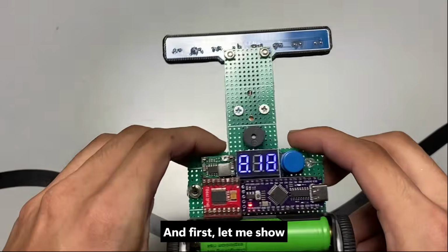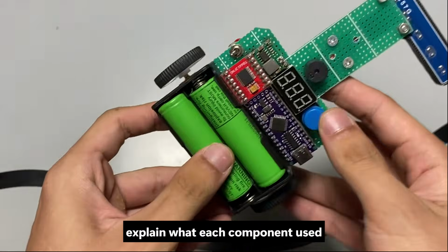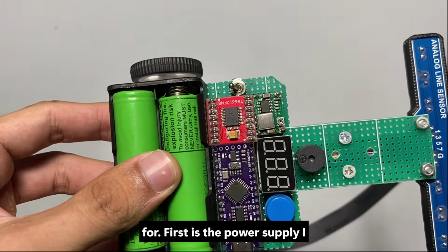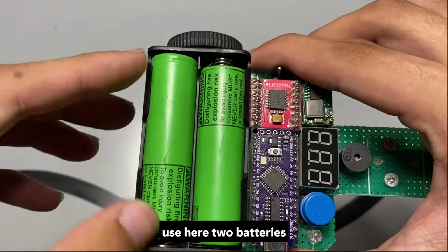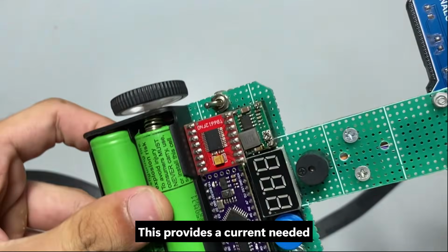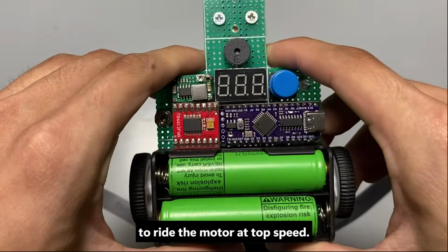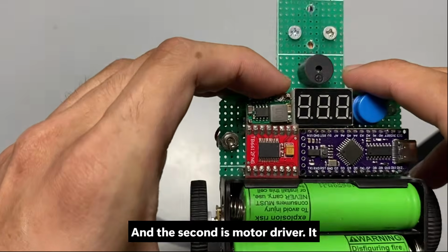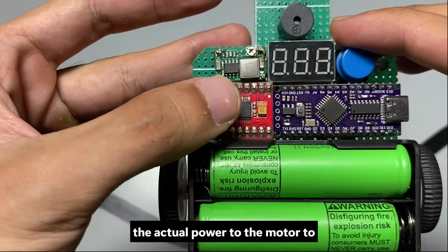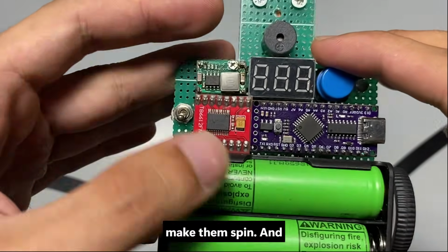And first, let me show you the structure of the robot and explain what each component is used for. First is the power supply. I use two 18650 batteries. This provides the high current needed to run the motors at top speed. And the second is the motor driver. It takes the signal from the brain and puts the actual power to the motors to make them spin.